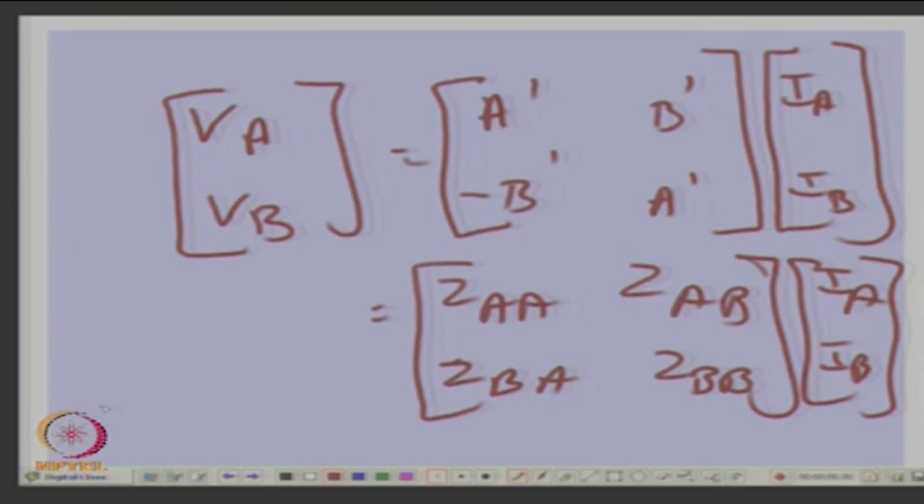So, we have defined the impedances now, and they will again be in terms of ZF and ZB. Now, we have a two phase machine. Now, you apply two phase balanced voltages, okay. Positive sequence and negative sequence you can apply. Is it okay? We have the impedance model level. We have these equations anyway, VA, VB equations are there and these parameters are there, okay.